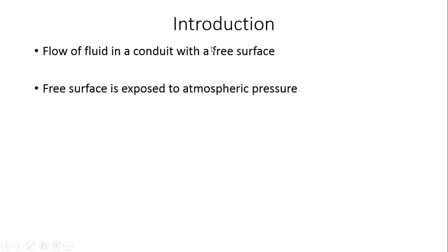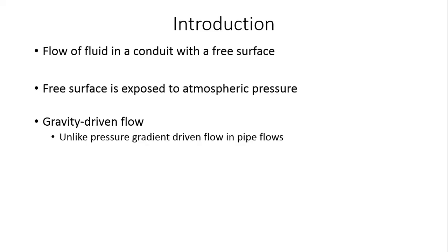Okay. Now, since it is a flow with a free surface, this free surface naturally is going to be exposed to atmospheric pressure, right? And then the other significant difference between open channel flow and pipe flow is that the flow in the case of an open channel is predominantly gravity driven, right? Unlike the pressure gradient, which is what drives the flow in pipes.